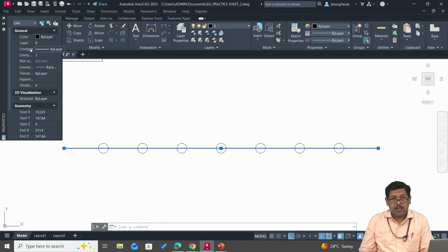In this, you have got the line type as the third option, after color and layer. Click on this line type, and you can see whatever line types we have just loaded are also visible. If you don't do that, it will only display the standard 3 default line types, which are ByLayer, ByBlock, and Continuous. Since we have added 2 more line types, it is showing those.